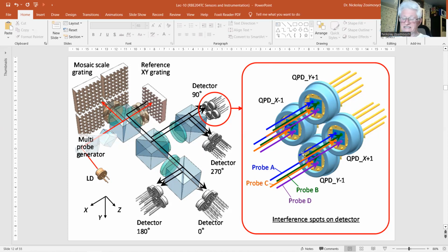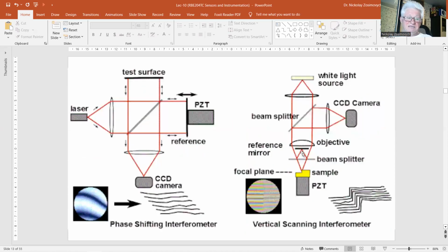allowing the construction of very small sensing devices. As an interferometer has a very high sensitivity to displacement, it requires a rigid setup and careful adjustment of the optical components. And furthermore, a frequency shift delta f induces an output change equivalent to a phase shift of 4 times pi times delta f over c. c here is the speed of light. I hope you remember, right?